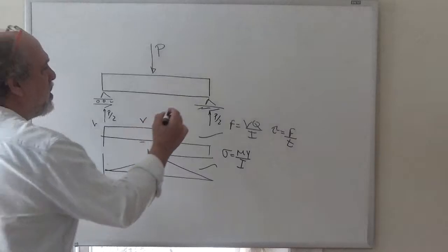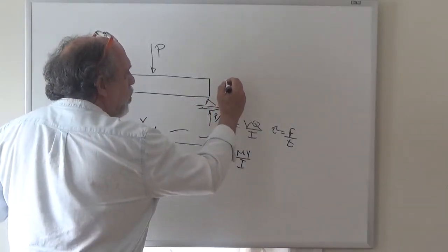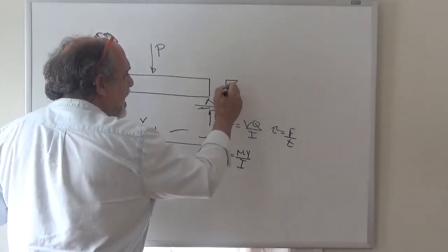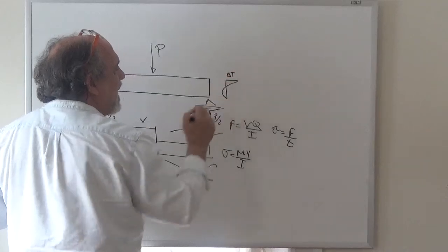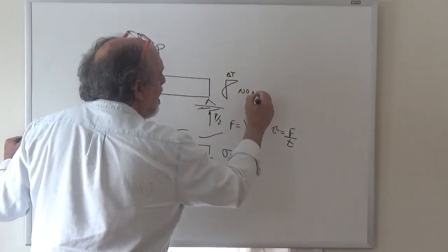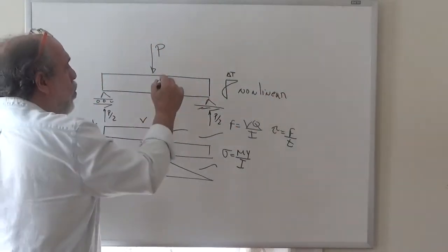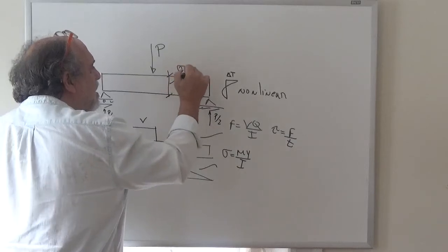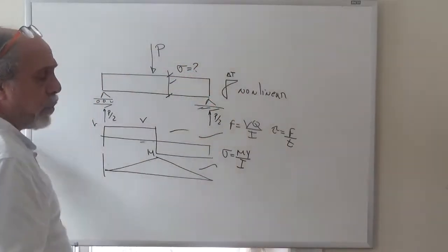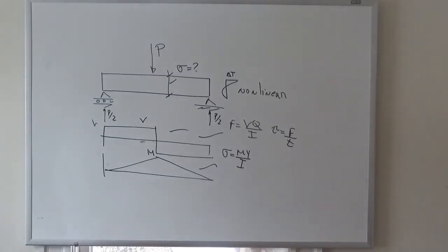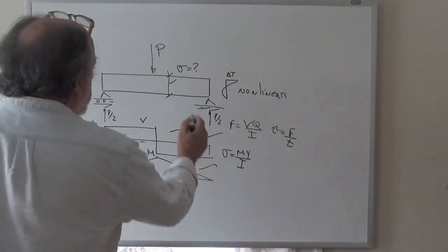you cannot come up with, for example, if I tell you that what I have in this beam is a temperature change that is like this. That is, I have a nonlinear temperature across the beam. Then if you wanted to know what are the stresses due to these temperatures, which we don't do because it's not a subject that is part of elementary structural analysis, or structural analysis to the level that we handle it in undergraduate. But if you had a nonlinear temperature distribution, there would be stresses in here.